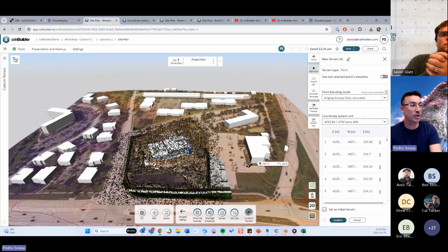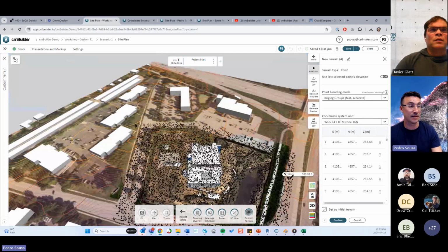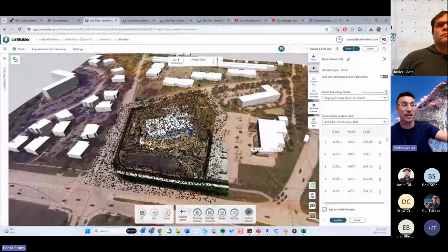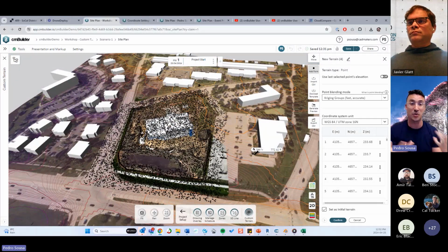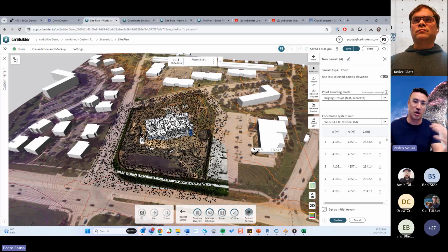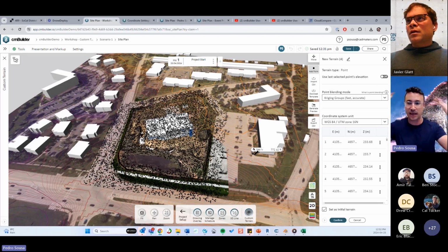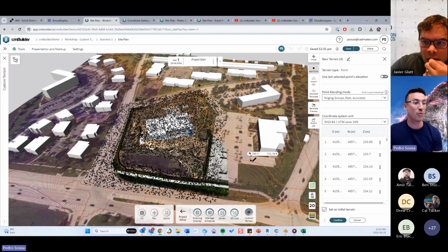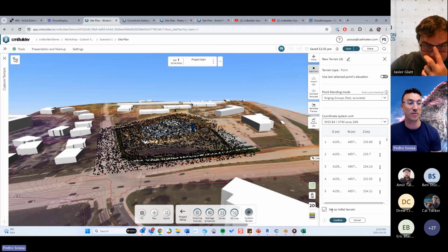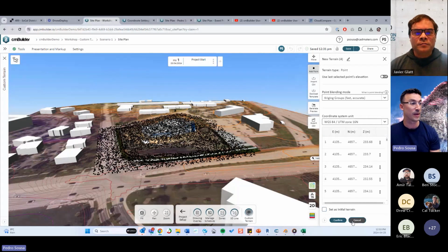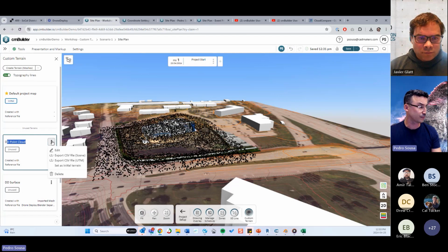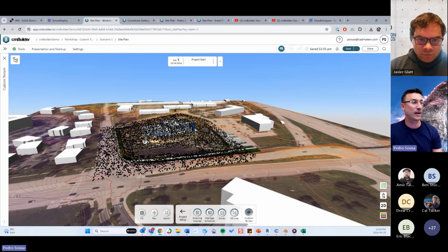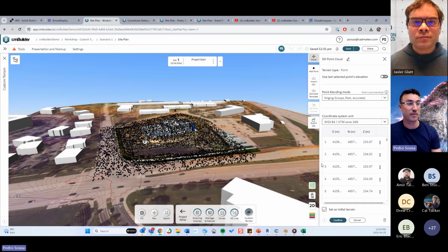After a while, my points are going to show up at exactly the location that I need them. This is super interesting and easy to do when you have a geolocated point cloud, because you don't need to manually position your GLB files, defining the elevation for them and things like that. Once you're done with this, you can simply hit confirm, and this will create a new point cloud for you. I already created one over here, and I can just select the DroneDeploy point cloud, and you can see that this is already defining the shape of my terrain.